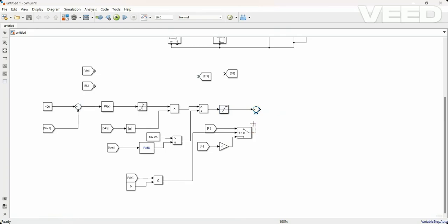And from here, we are again comparing it. So if you see, what we have done is this upper loop is taking in the DC references and going through the PI loop. Then we have an AC voltage reference, so we multiply it with this error. So we essentially get magnitude as well as a complete sinusoid coming here.